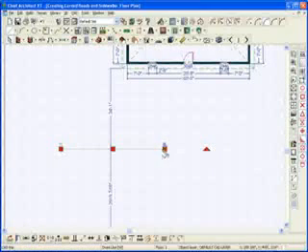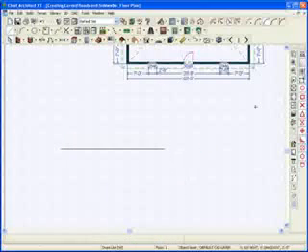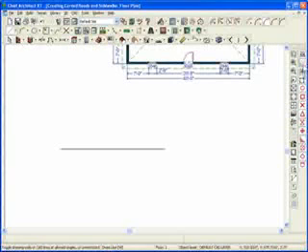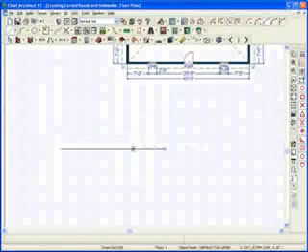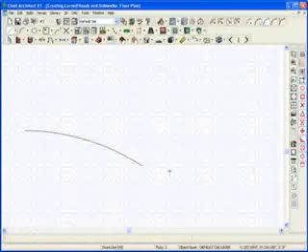I'm going to grab this end handle right here, and I'm just going to hold my Alt key down. I'm going to bend that line into an arc. First of all, you'll notice it snaps now. It's snapping at specified degrees, 15 degrees. I could go up here and turn that unrestricted angles setting off, and now when I grab that line and hold my Alt key down, I can bend it pretty much unrestricted any way I want to. So I could turn that line into an arc.